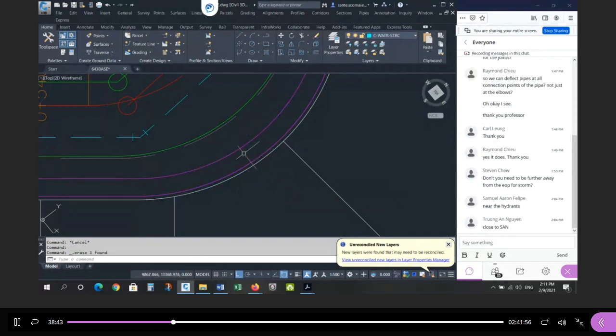Okay? I wouldn't certainly vary both dimensions, right? I wouldn't put it somewhere between, but I would make it either parallel to this line or parallel to this line. And make a decision. I wouldn't make the sidewalk vary. You want the sidewalk to be a constant width of 1.5. Okay, so this is my preferred solution. So you could do it either way, but then if you came to me for advice, I would say, please do it this way. And sometimes the only reason you're going to get from me is because I said so.